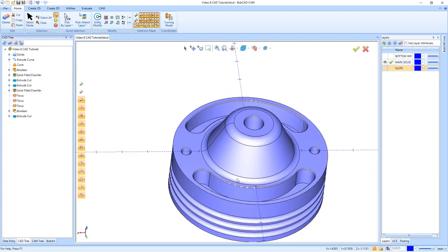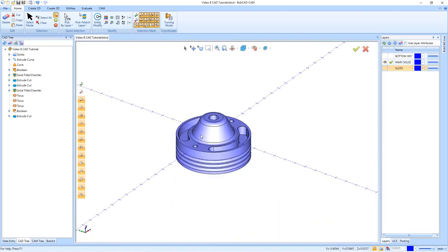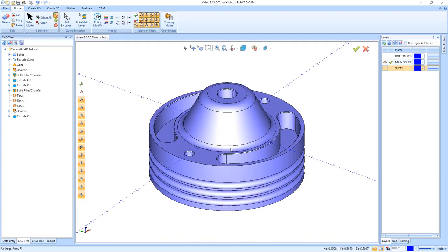Now to set it up so that when we save it, we get a good preview for the next time we want to open up, make sure to do a save as and save it as a file type. But before you do it, set it to a good view. So I'm just going to go up to my views and set it to an isometric view, because when we save the file, we kind of take a screenshot of it in the position that it was in the last time it was open. That way, when you're reopening these files, you get a preview of the part.